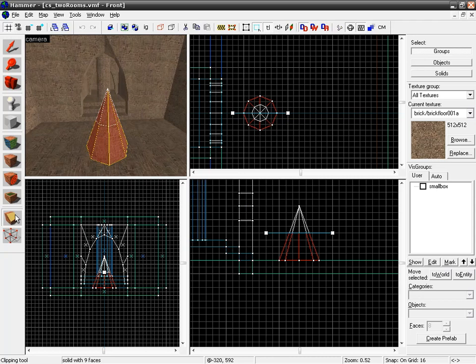If you click the clipping tool again, you'll notice it switches. The white and red flip. So now we have a white base and a red top. And if we click again, it's white on both sides, but we still have a line right down the middle. What the clipping tool does is cut an object or a brush right down the line that we draw. And the white objects are going to remain in our scene once we press the Enter key. So in this case, we would cut the object. We would actually still be able to manipulate both.